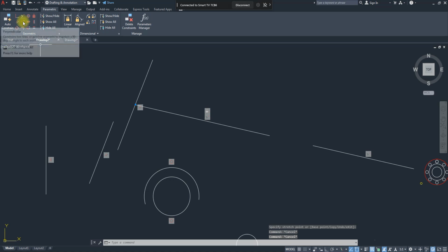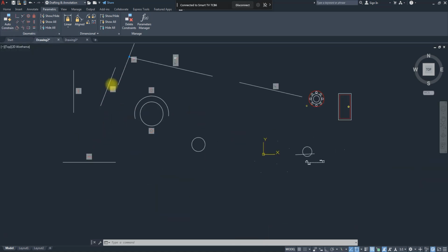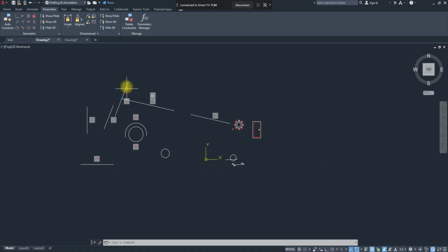Then you have perpendicularity, so you want them to be perpendicular. So if I want this line to be perpendicular to this line, I can also do that. Okay. But if I do that now, that means I won't be able to move this anymore because this will always be horizontal. Let me show you what I mean. So if I say perpendicular, this will be fixed, while this will jump. Because if I try to use perpendicular and I click this first, it will not work.